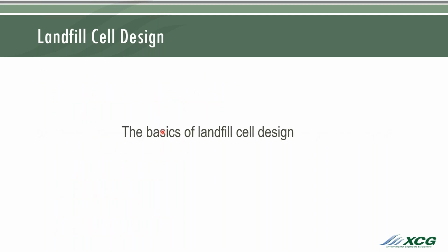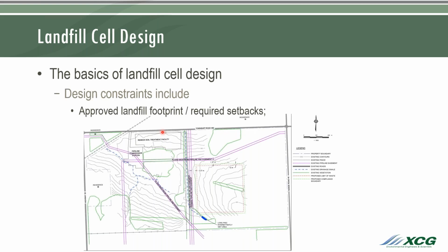So the basics of landfill design. A lot of a landfill design is made up of the area that you can put your landfill. In this case, the area that I'm highlighting with the laser pointer is the entire landfill, not just the cell. What I wanted to show here was setbacks and the landfill footprint, so the outline of the landfill. With this example, we were constrained by a handful of gas and oil pipeline easements. So the actual facility that required the landfill is up over here, and we decided to put the landfill over in this corner.